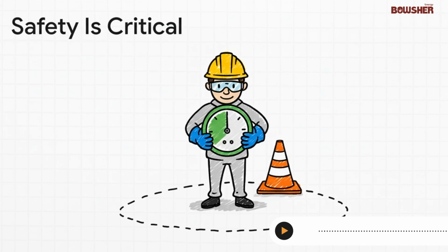Now, even though it's a low-pressure test, safety is absolutely non-negotiable. Professionals always use controlled pressurization, carefully calibrated gauges to monitor it, exclusion zones to keep people safe, and of course the proper protective gear for the technicians doing the work. Remember, simple does not mean careless.